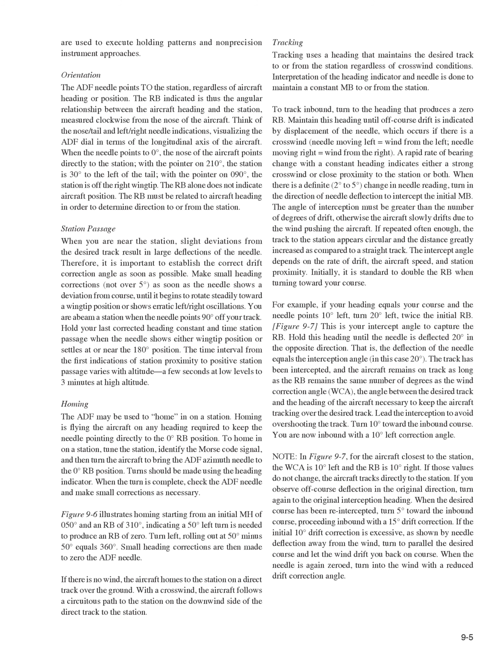With the pointer on 210 degrees, the station is 30 degrees to the left of the tail. With the pointer on 090 degrees, the station is off the right wingtip. The relative bearing alone does not indicate aircraft position.